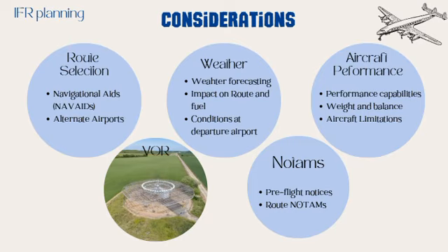Each aircraft has specific performance limits for speed, altitude, and the ability to handle certain weather. For example, some aircraft may have lower tolerance for icing conditions or require higher cruising altitudes to avoid turbulence. Dispatchers consider these limits and select a route, altitude, and alternates that align with the aircraft's capabilities. Together, these factors ensure a well-prepared IFR flight, minimizing risk and enhancing the ability to handle any unexpected change in route.